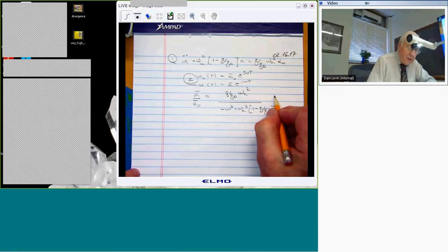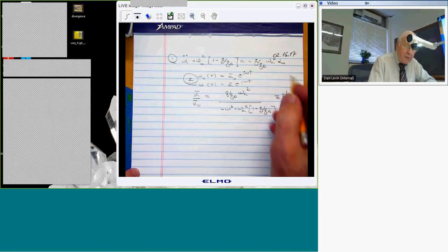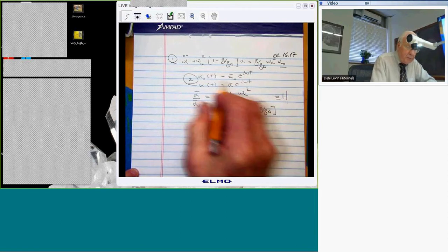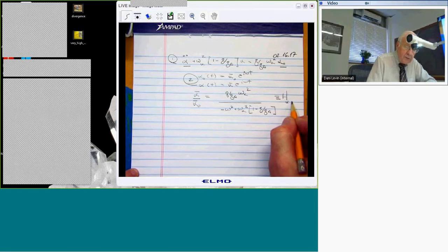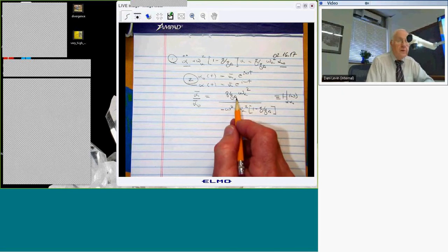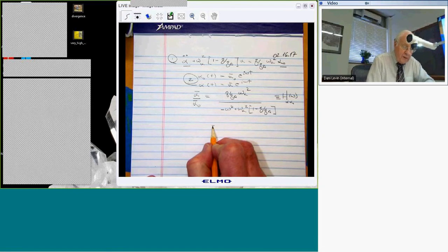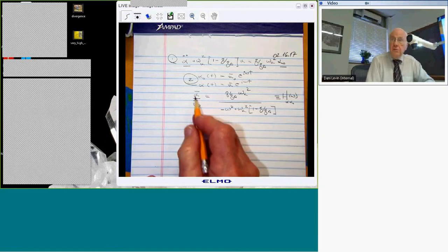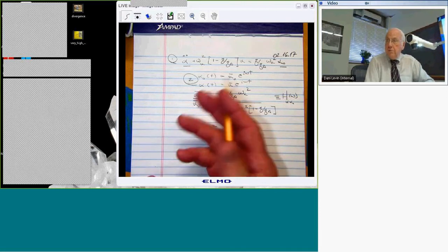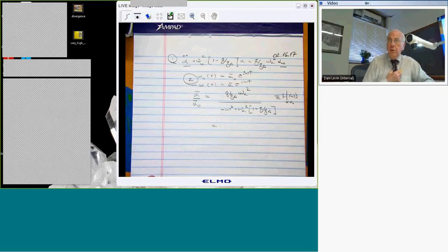And we define this to be the transfer function that transfers the amount of the input, alpha naught, to the output, alpha. So we put 2 subscripts on it to denote that, and we want to emphasize that it depends on omega. Of course, it also depends on Q over Q sub d, right? In fact, let me write this one other way, just for fun. This is a non-dimensional left-hand side, right? Well, alpha itself is non-dimensional, but even if it weren't, by the time we make a ratio, it will be non-dimensional.